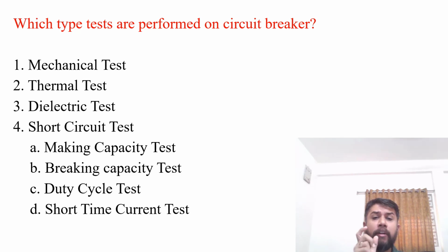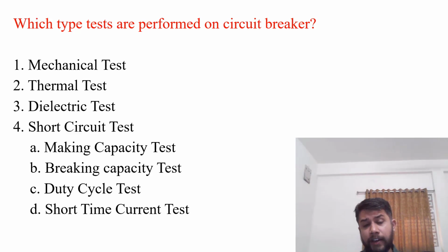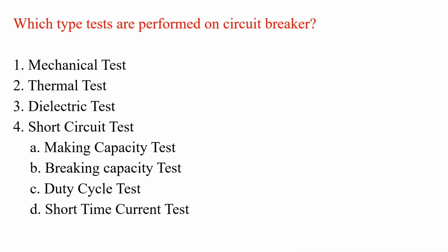Which type tests are performed on a circuit breaker? If this question is asked in the examination, you have to answer like this. First is the mechanical test conducted on the circuit breaker. These are type tests: thermal test, dielectric test, short circuit test, and in the case of the short circuit test there are certain tests like making capacity test, breaking capacity test, duty cycle test, and short time current rating test.